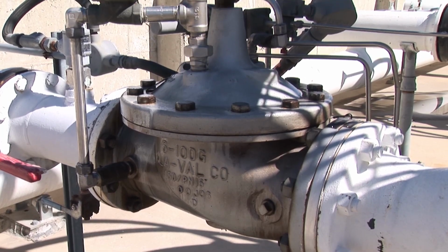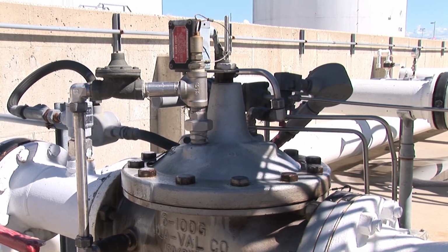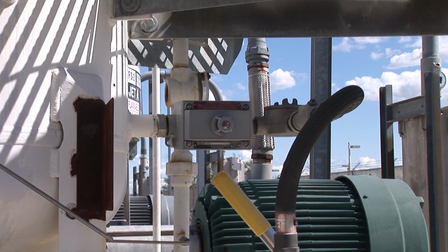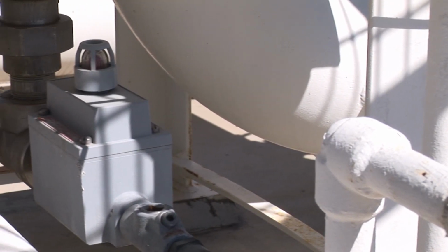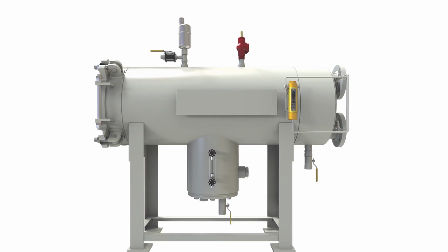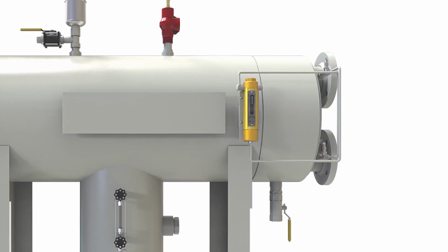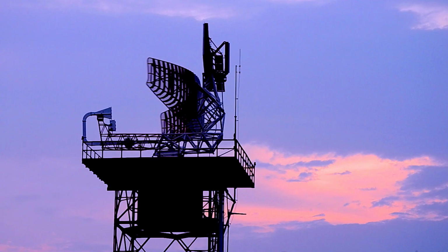This water defense system can automatically stop the flow of fuel if excessive water is detected. It's triggered by either a pilot-operated float or an electronic probe. In cold climates, you might come across heater thermostats on the water sump and drain lines. And this direct reading pressure gauge is certainly one of the primary accessories. Its readings help you determine the condition of the cartridge and the remaining life of the elements.